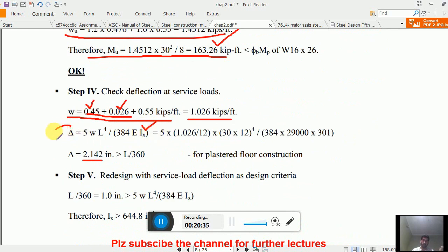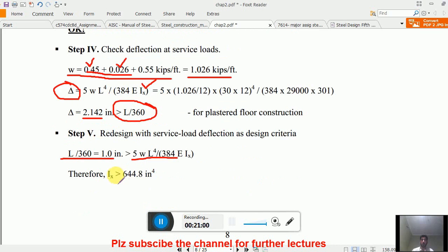Fix a deflection value, that is L by 360. Find out this L by 360, plug the value of L by 360 here and find out IX. Go to the IX table and choose such a section whose IX is equal to or larger than this one. Clear? So that did the same step. L by 360 is 1 inch, which is greater than 5W, this one. So they find out IX from that formula as we did in lecture number 11.